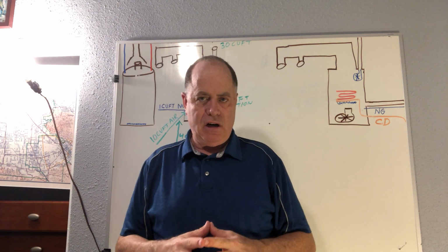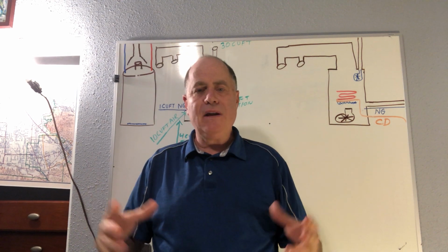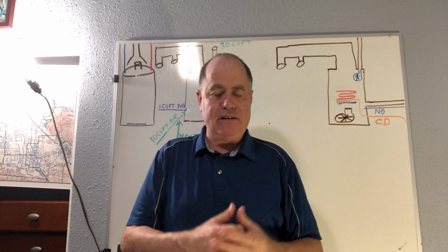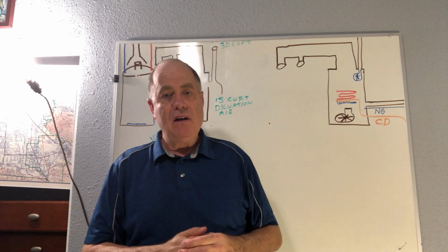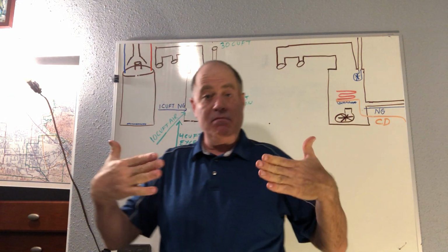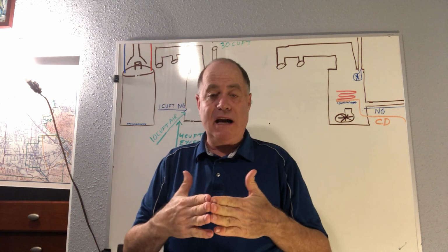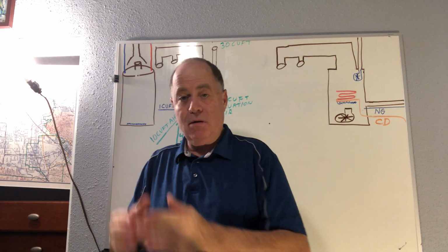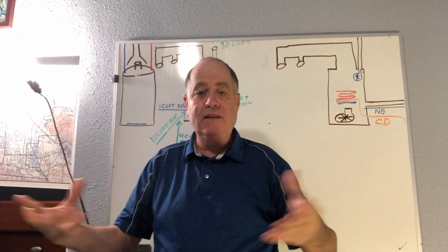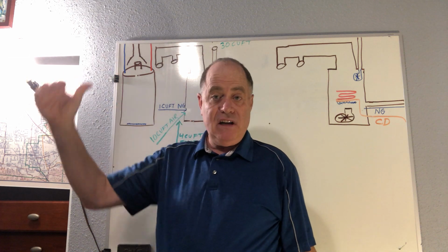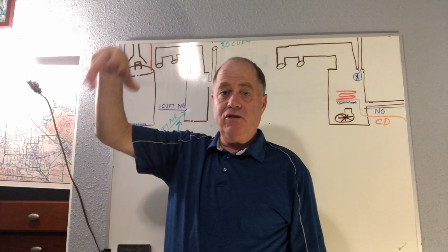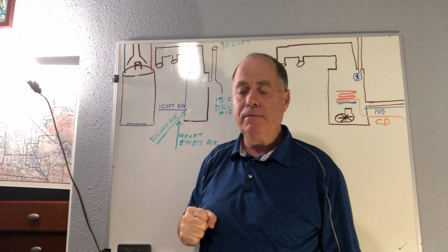What is combustion air? It's all of the air that a heating appliance needs to operate safely and properly. It's the air that needs to come in and mix with the fuel, let's say natural gas, to have proper combustion, extra air to move things along, and lower the humidity of the products of combustion so it can't condense in the flue pipe.